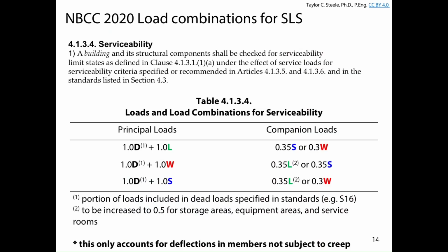So in this case, we use a different table. We use these load combinations. We've got dead plus live. And if it's important, snow and wind. Really, for beams, we either have interior joists and girders that carry dead and live loads, or we have roof girders that basically are going to carry dead and snow loads, right? Dead and snow loads, that one.